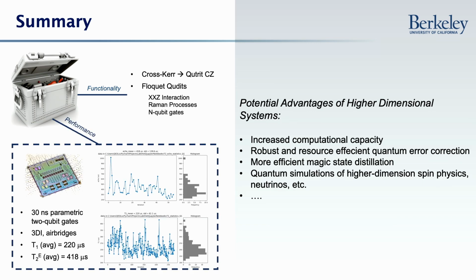And then as we look towards the future, we really want to improve the fidelity and performance of all of these underlying operations. So we're really pushing hard on test devices to improve our coherence. And we've also been integrating parametric couplers and are interested in studying them for 2-qubit gates because we've already been able to achieve much faster 2-qubit gates using them.